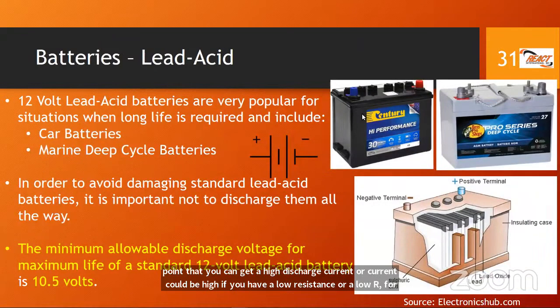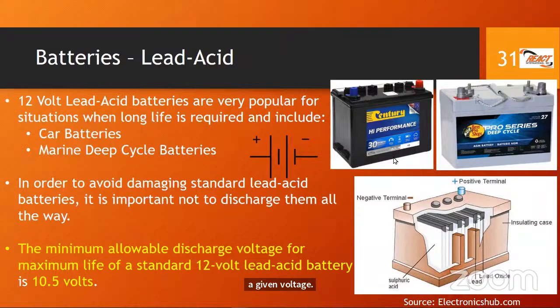Right, so another type of battery, you may recognize this, you say, wait, this looks like the battery you'll see inside of a car or vehicle, right? So yes, if you have a boat, you see something like this. So we have the types of batteries, car batteries, what we call cranking or starting batteries. And then we'll have the other type of batteries that we call deep cycle batteries, often used in the marine environment or even for UPSs, right? Because they can be discharged a little bit lower. As a matter of fact, the difference between the two often is the thickness of the plates that they are constructed with.